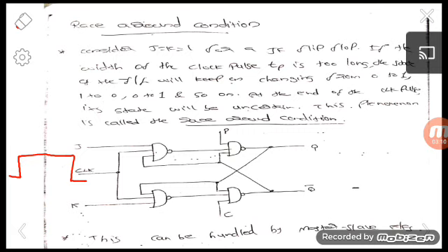This propagation delay is there for any digital logic gate. So after applying the inputs, the circuit will take some time to produce its output. If the width of the clock pulse is greater than the entire propagation delay of our circuit, we can't predict the output of the flip flop. It will keep on changing from 0 to 1 and 1 to 0, and so on.